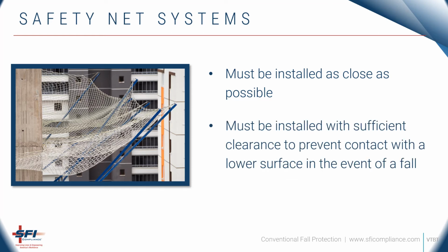Safety nets must also be tested after installation to ensure there is sufficient clearance, which will prevent contact with a lower surface. The most recent certification record for each safety net and net installation must be made available on the job site for inspection.